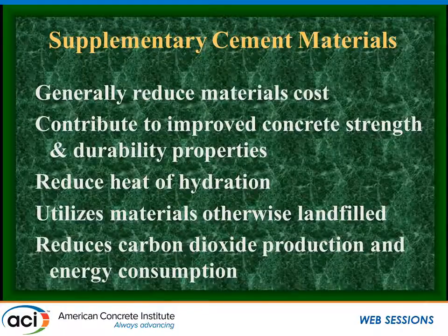Well, as we used more and more of these materials, we found not only were we saving some money, and this is kind of counterintuitive, we're getting a waste product that's cheaper, but we're actually making better concrete with it. We found that not only could we get some economy by using these recycled materials, we find that they also contribute to improved strength and improved durability properties, lower permeability, reduced heat of hydration. So now we've got a performance advantage.